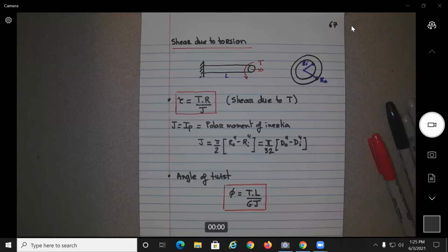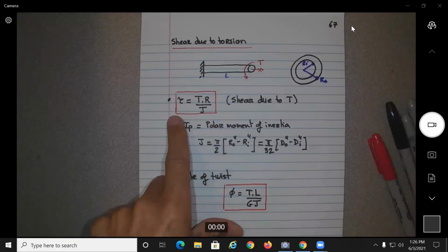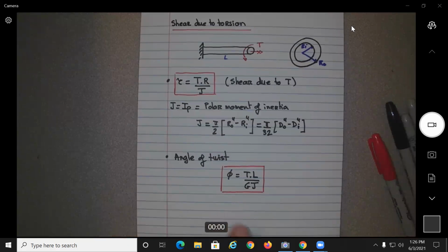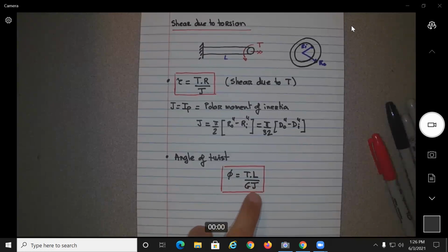But now, what is the problem? And that is a problem that many times some of the teams over here have, the Baja and the other one. They base everything on the shear, so it looks wonderful, we can save a lot of weight, but then what happens with the angle of twist? You want the angle of twist to be small, no? Otherwise, if you attach gears, which is what they generally do to the transmission shaft, it is going to skip, no? So you see, if J is small compared to the one of the shaft, then the angle of twist will be higher.